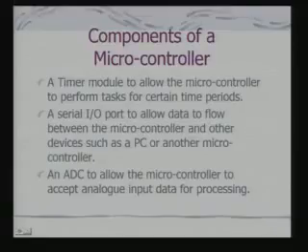We have, on top of parallel I/Os, serial I/O ports which allow data flow between the microcontroller and devices which support serial interfaces. The serial ports are also used for interfacing with the PC during the development life cycle of the embedded system. As well, when we need to use the embedded appliance with the PC to read data or reprogram it, the serial port is also used.